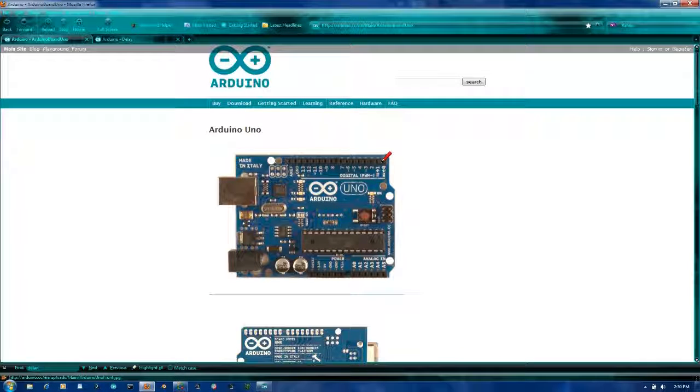This is RX and TX. This is the same thing as you saw with these lights over here. This is receive and transmit. So not only are they digital pins, but you can plug into another device, like a GPS or any other device, actually, and have it communicate to and from the Arduino using those. Or you could use a soft serial library and make any of these pins transmit and receive to talk to other devices. When we get into the code for the university, we built a GPS for the bus system that I'm going to review with you and publish all that as well. But anyways, back onto it.